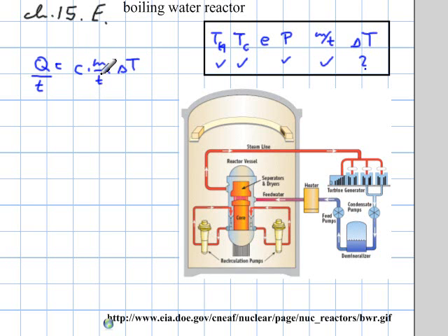So now I have a known here, and I have a known here, and this one here is my unknown, my variable, and this one here is kind of known as well because it's the heat that goes into the river per time unit per second, and that one is determined from the efficiency, which we determine in a moment, and the total output, the power. Okay, so let's do the efficiency next. The efficiency is, of course, for a Carnot engine, 1 minus Tc over Th.